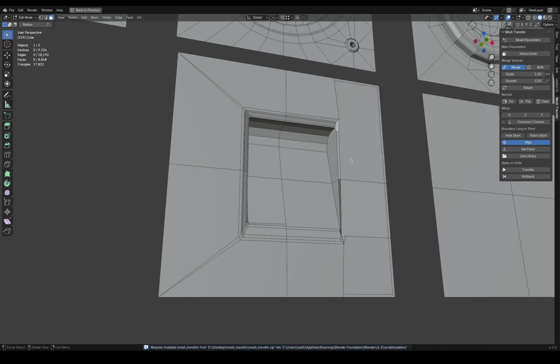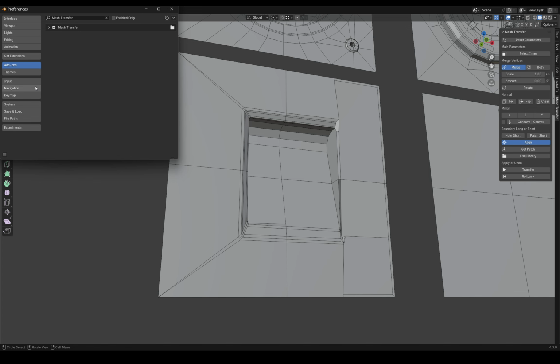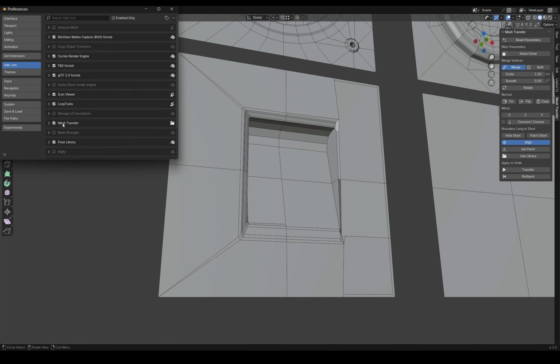To install the add-on, you just need to drag the zip archive into the program window and click OK. After this, a panel with the add-on will appear in your 3D window. To remove the add-on, you need to go to the Program Settings, then go to the Add-ons tab. Find it there and click the Uninstall button.